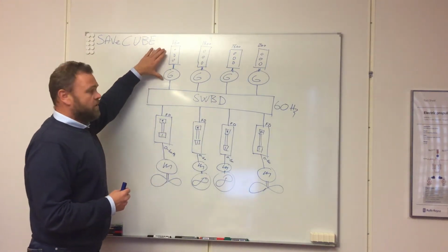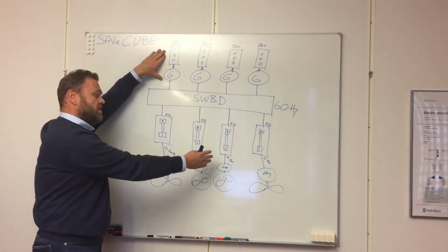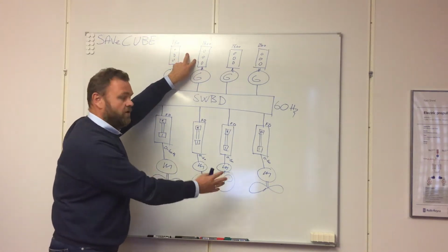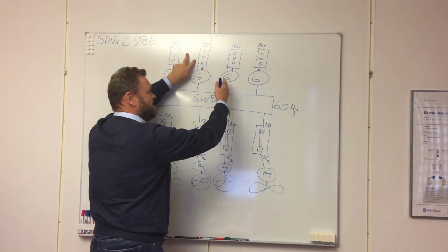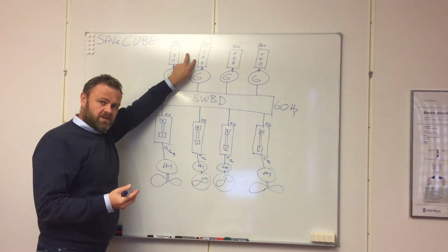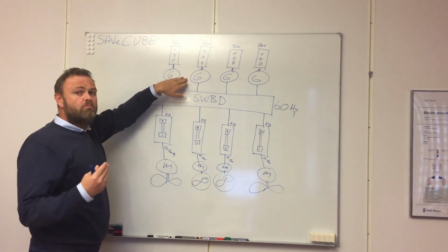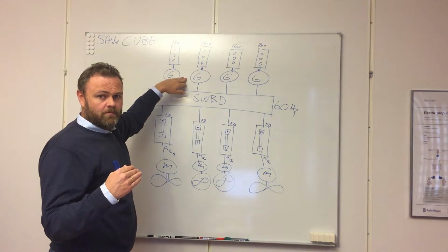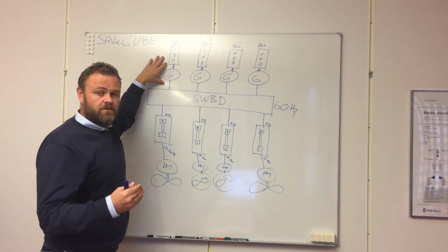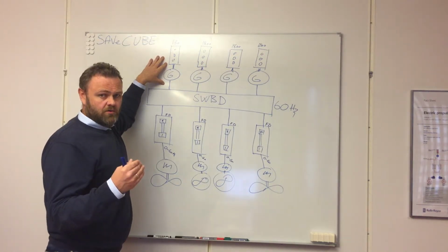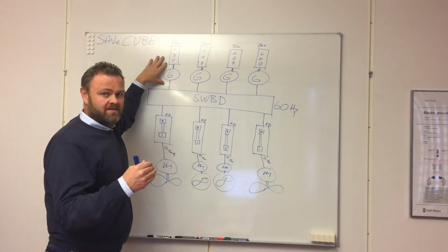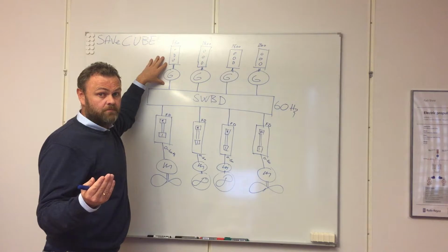So you start with one engine. Do you need more power down here? You start the next engine. If you need even more power, you start the next engine, and so on. That gives you the opportunity to run the engines closer to the optimum, because it's better for the engine and for the fuel consumption to be close to 100% load than to be at 20% load.